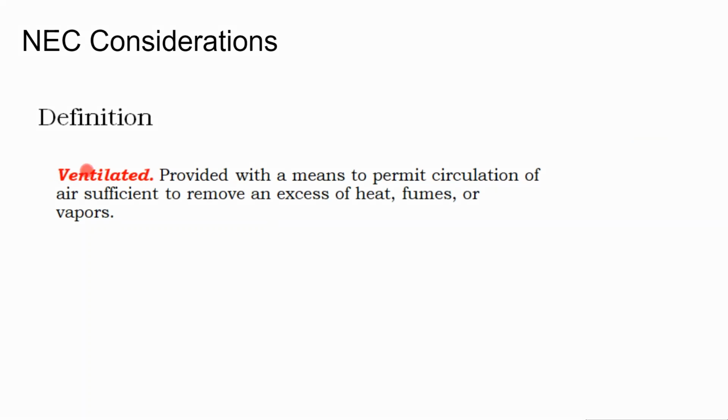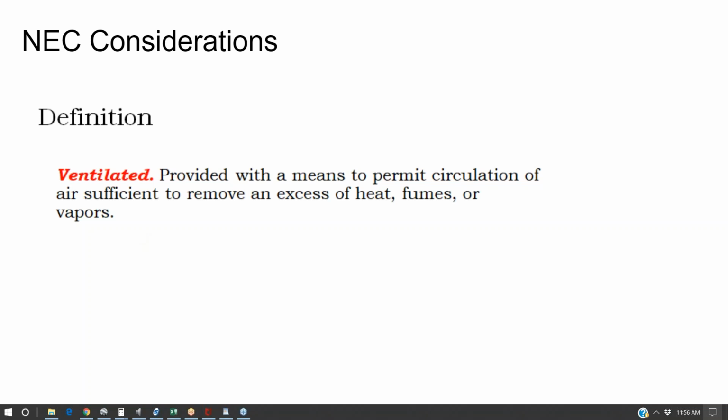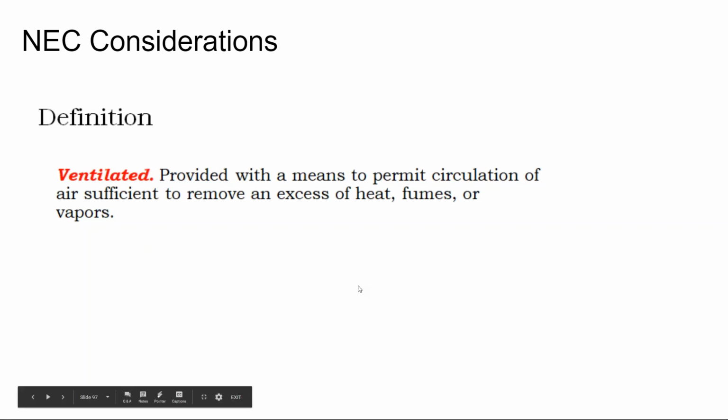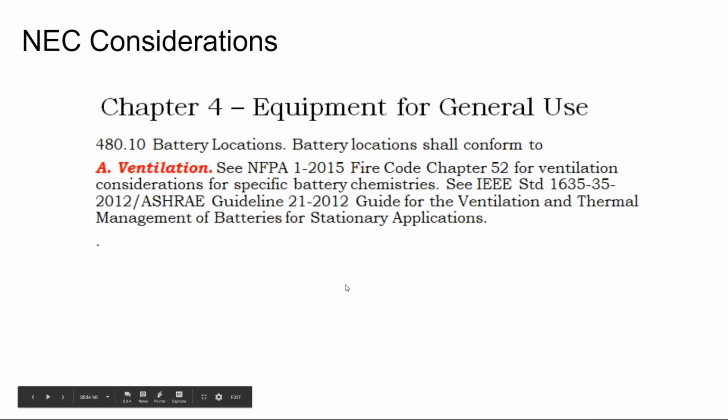Another thing is the rooms have to be vented. Your unsealed flooded lead acid will emit gas, particularly when it's being used and charged, and that gas is explosive. So it needs to be kept to less than a 3% air concentration. And so your space has to be vented.